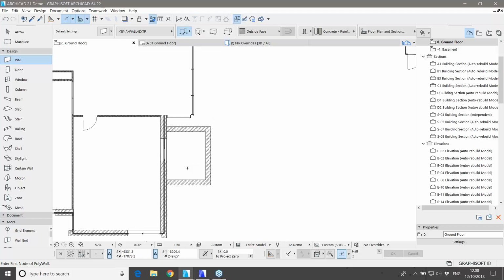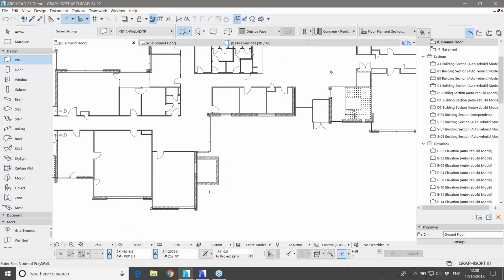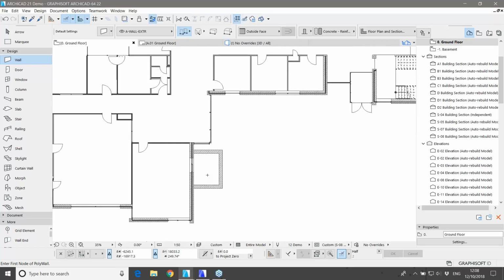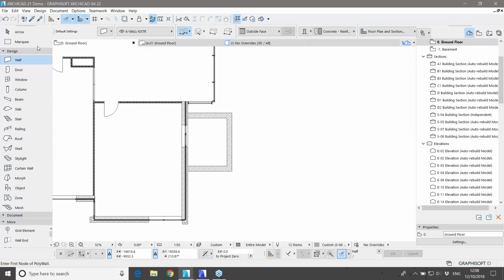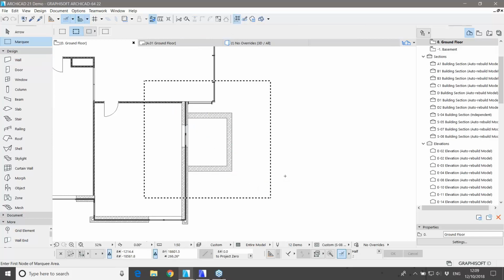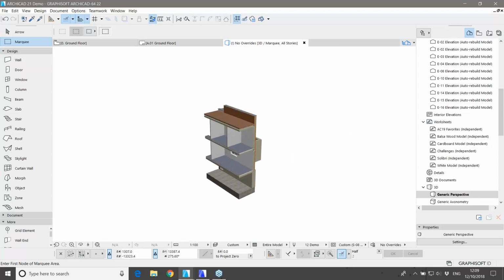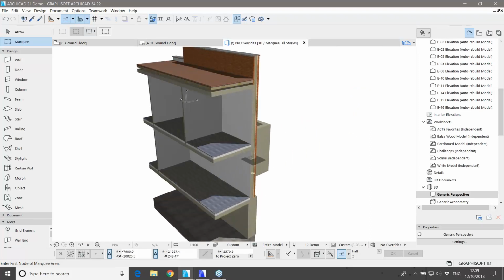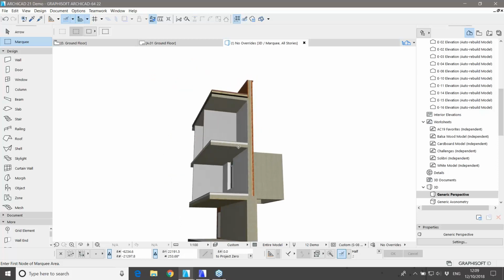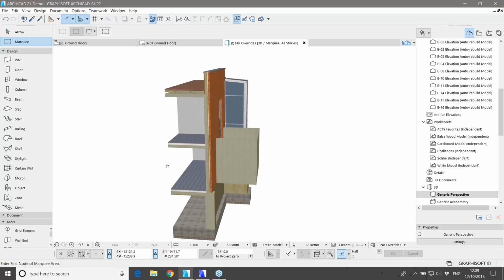Let's see what I have placed in 3D. So this is a big model, and I'm just interested in the extension that I'm working on at the moment. That's why in ArchiCAD, we've got a tool called Marquee, which will give you partial 3D cutaways. If I just place a marquee around wherever I have worked and switch to 3D now, you will notice instead of the entire building, I can now focus on the bit that I'm working on. It's easier to navigate as well, in case you're working with big commercial projects.